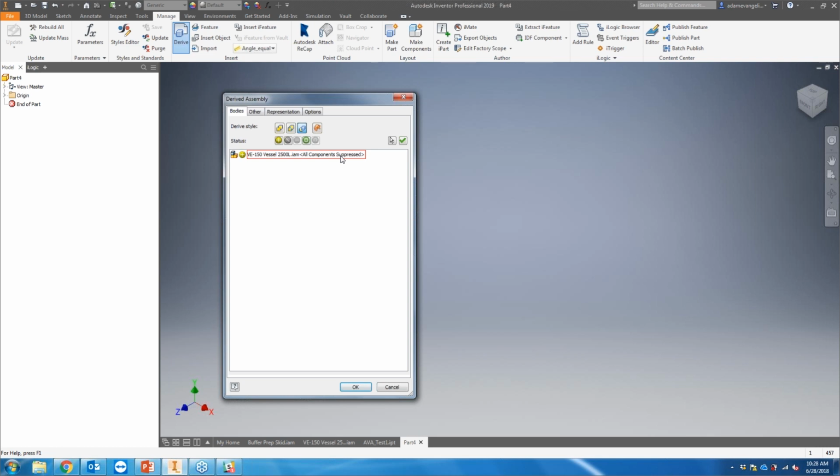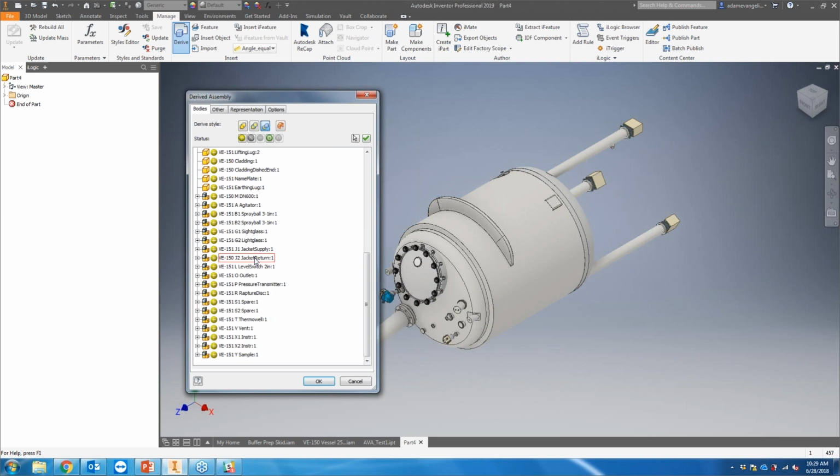I'm going to go back to this first page, and you're going to see this whole page got kind of populated over here with a whole design tree. And so again, this is going to be a whole list of all your different parts in your assembly and everything like that. There's going to be a few more colors here. Again, we're going to see derived style, and we're going to see the same buttons that we saw in Shrinkwrap. Right, we can make single bodies, multi-bodies, composite bodies.